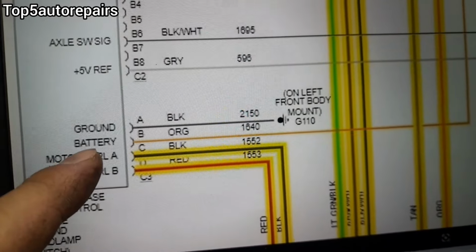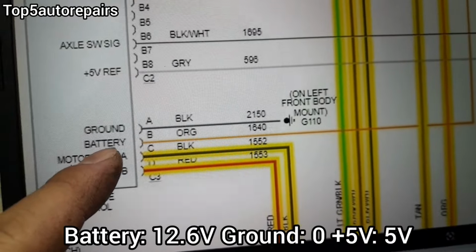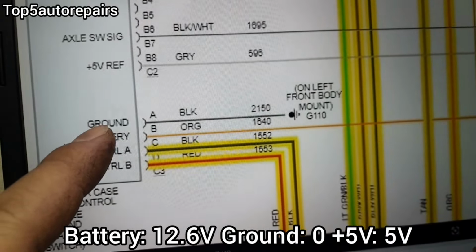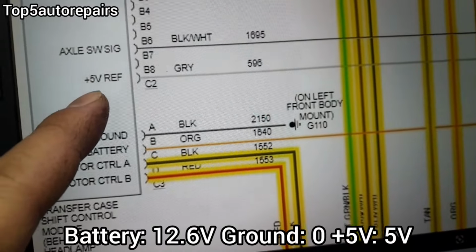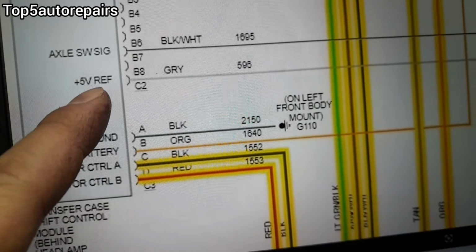So most importantly, make sure we have power, which is a battery that's going to be 12.6 volt. We're going to have ground, that should be 0 volt and 0 resistance. And we have the 5 volt reference wire, that's going to be the signal wire. Now let's test the wire on the transfer case control module. Let's make sure the wire is good.